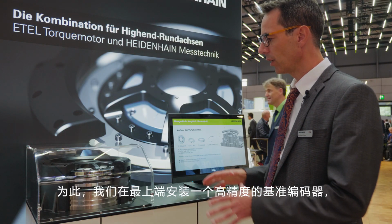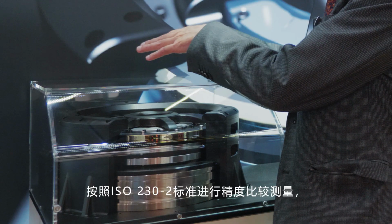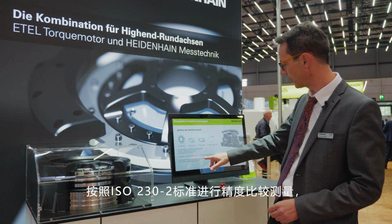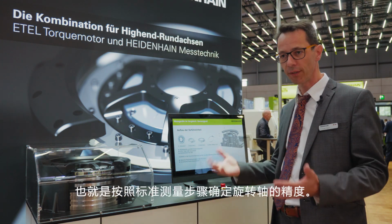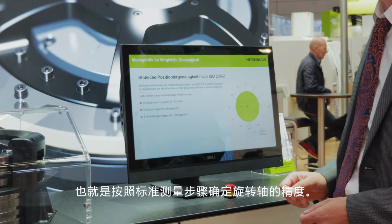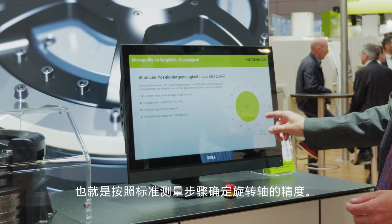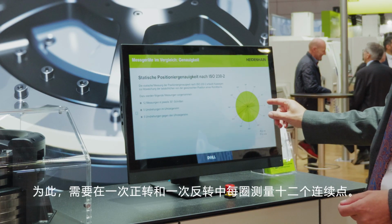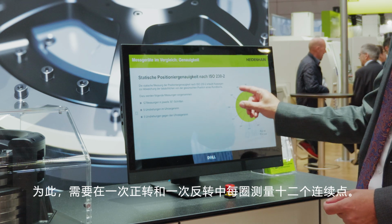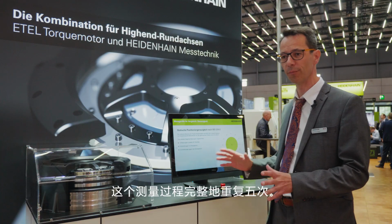To do this, we mounted a high-accuracy reference encoder on top and performed a comparative accuracy measurement in accordance with ISO 230-2, which is a standardized measuring procedure for determining the accuracy of rotary axes. It requires measuring 12 consecutively approached points per revolution, with 1 forwards and 1 backwards revolution. This entire process is repeated 5 times.